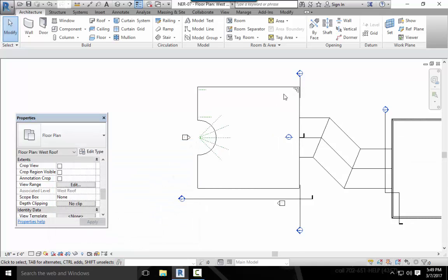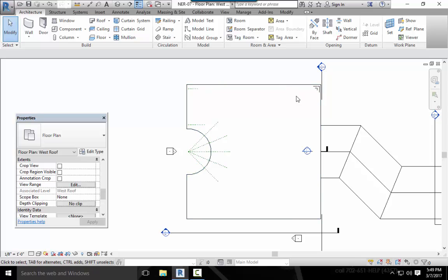Okay. Now I can see my entire roof, right? Still have a problem with the walls. Alright, so now what we need to do is fix the fact our walls poke up over here and they don't connect over here. Just after figure 7.44, of course, there is a wall issue. You can attach most of the walls to the roof by simply selecting them and attaching the tops, but you'll have to modify the profile of one wall as follows.